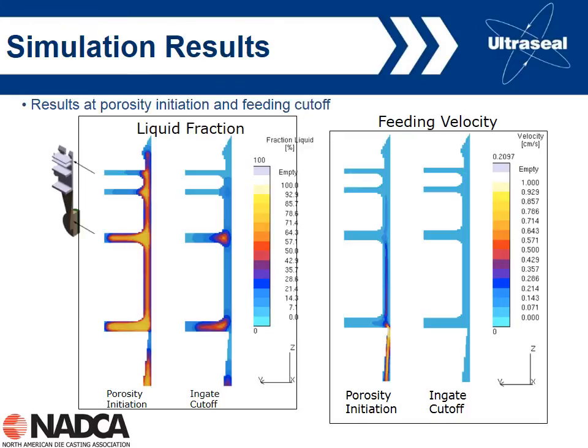We've got a pocket here, maybe a little bit here. So basically, we know the volumetric shrinkage is 6%. So basically, 6% of this remaining liquid is now going to be porosity, whether we like it or not. So that's kind of another point on this.